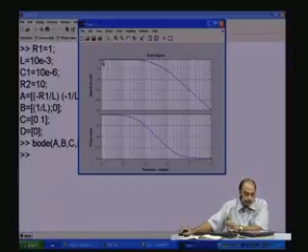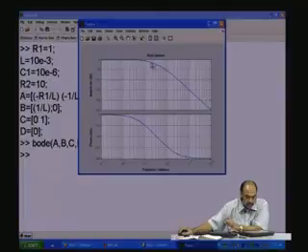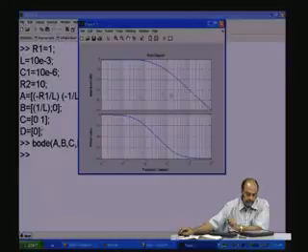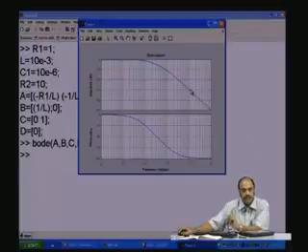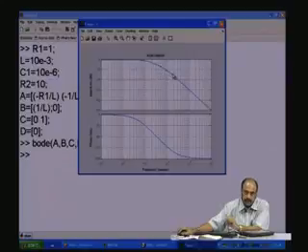Now, one thing that you should notice here is that, of course, though it looks very similar to the RC circuit, the slopes are different. Here the slope is for 1 decade from here to here, it has gone down by 40 dB, whereas in the earlier circuit for 1 decade from here to here, it would have gone down only by 20 dB. The slope was minus 20 dB per decade, whereas here it is decreasing at a much faster rate. So, it is a much sharper filter.